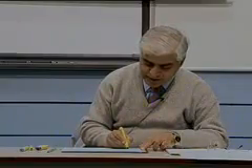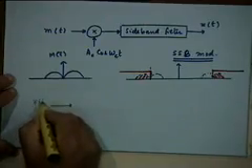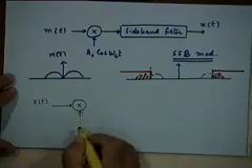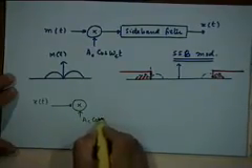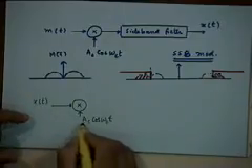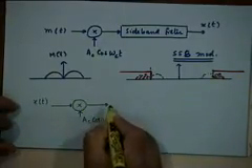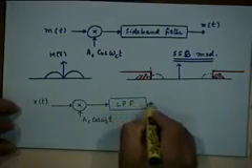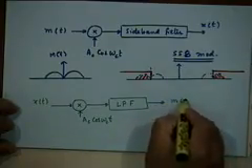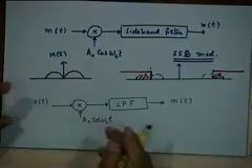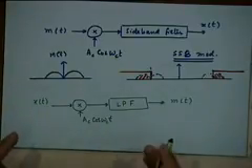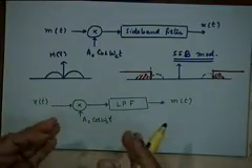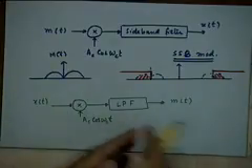Convince yourself. So what I am saying is, as far as the demodulation is concerned, take your modulated signal x(t), multiply it with a coherent carrier which is in phase and frequency synchronism with the incoming carrier, and pass it through a low pass filter, and you will get your message signal back. Is that obvious? Look at it in the frequency domain, it should become obvious. When you are multiplying with Ac cosine omega c t, remember what is the operation you are doing? You are carrying out a frequency translation by minus fc and plus fc.